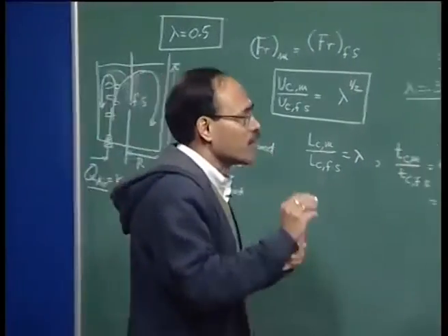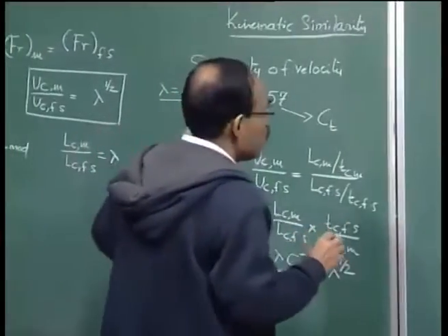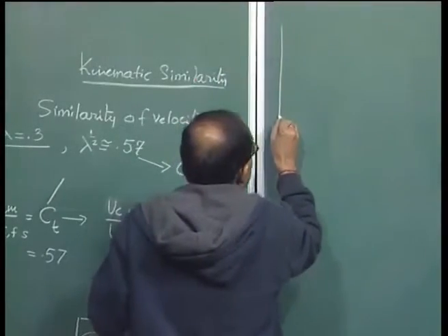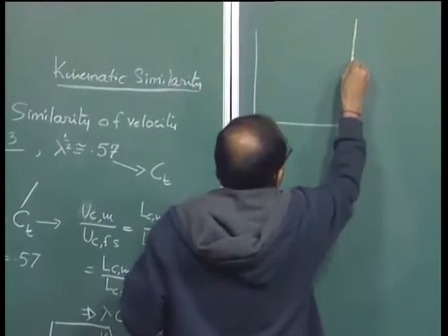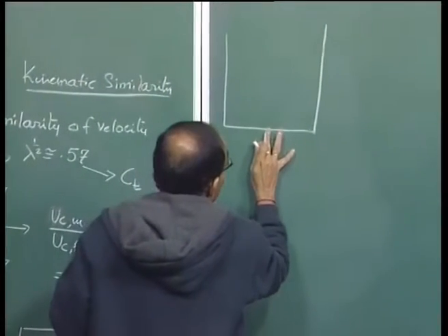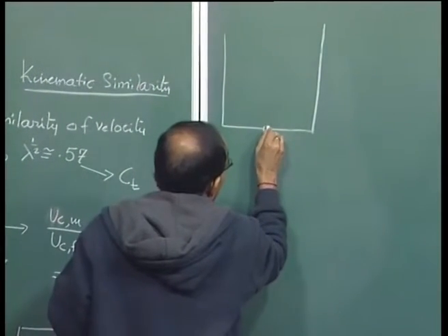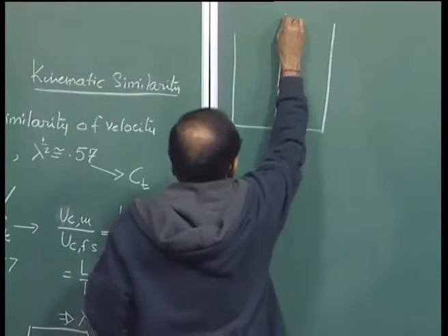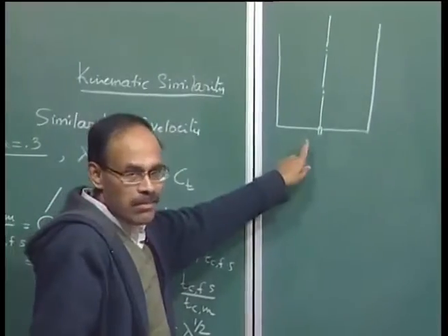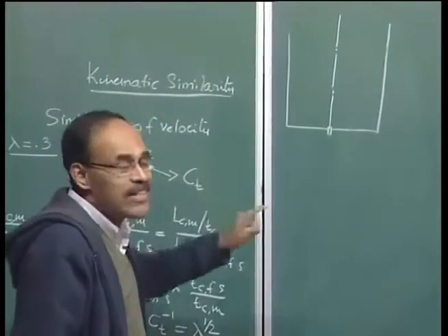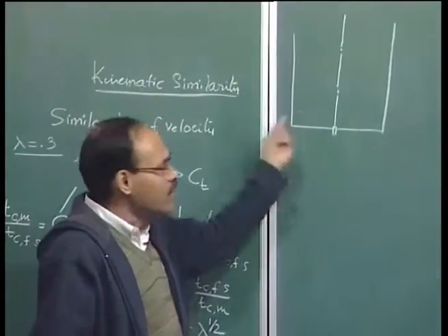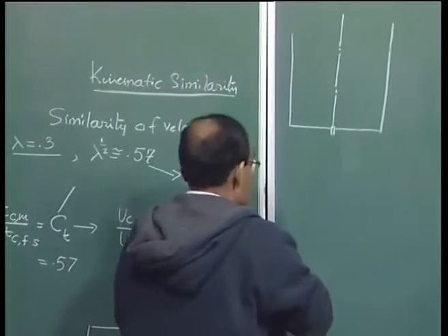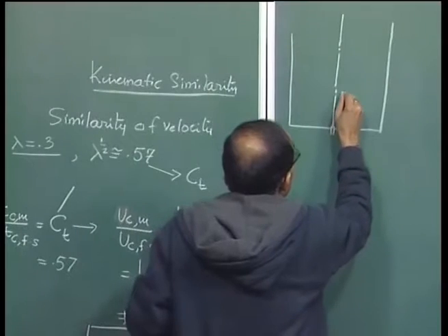So, let us for the time being demonstrate by considering a central gas stirred ladle system. By central gas stirred ladle system, I mean that I have a porous plug or a nozzle which is located at the central line. The theories are well understood about central gas injection, even though central gas injection is not practiced in the industry. So, we have something like this, a two phase plume which develops here.